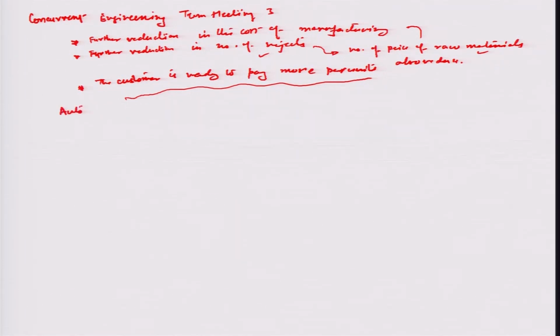This is a much better controlled option. It has a much lower standard deviation. If you may recall, in this particular case, the standard deviation corresponding to an automatic screw cutting machine, ASM, comes out to be equal to 0.001. So, the sigma j in this particular case comes out to be 0.001. Mean, of course, is the same shaft dimension which was used in the earlier examples.